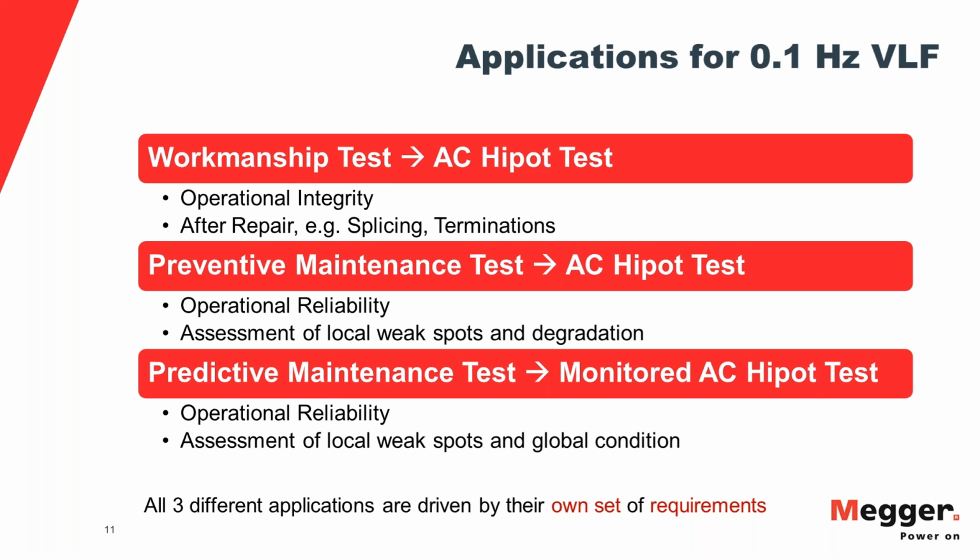A few months ago, I had an expert seminar with some of our customers in Slovakia, and they don't do tan delta testing for the first 7 years after installation, because you will get misleading tan delta readings, because there's no water in the cable. It's a new cable. It still gases out. You have these chemical settling processes in the insulation. So their experience is, if we start doing tan delta after 7 years, then we're okay. But that is already in the service aged stage.